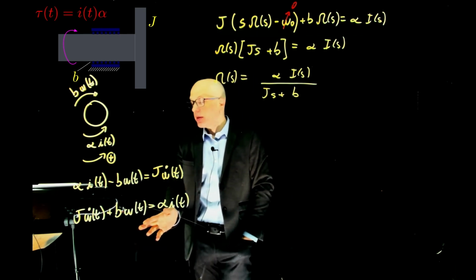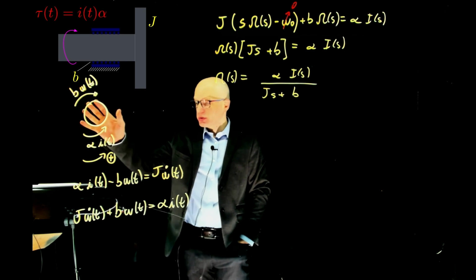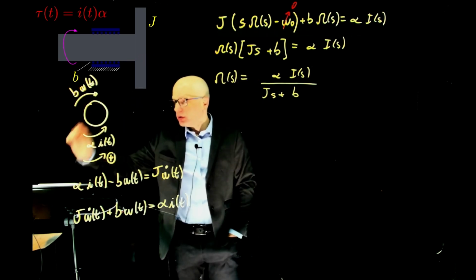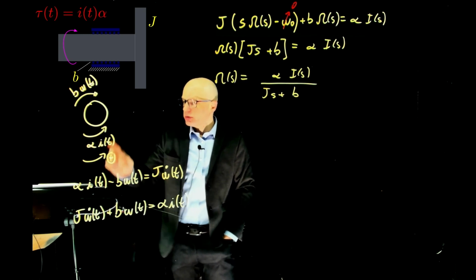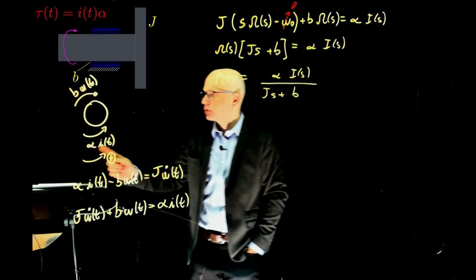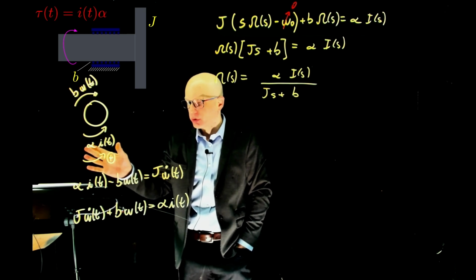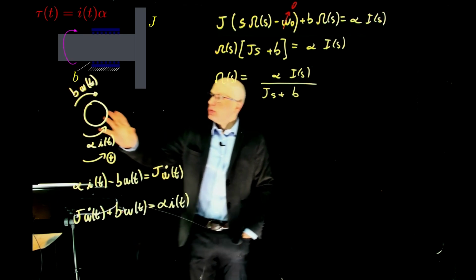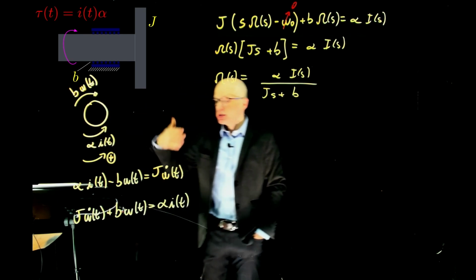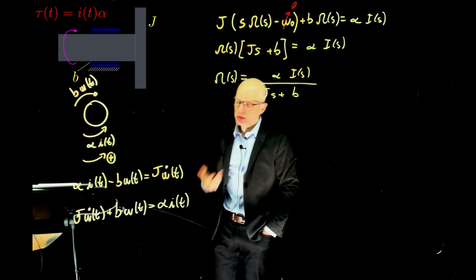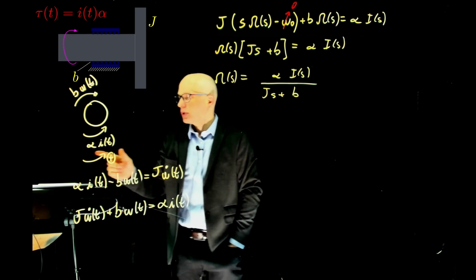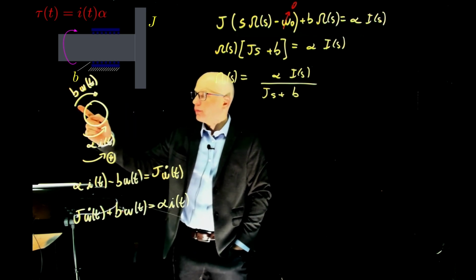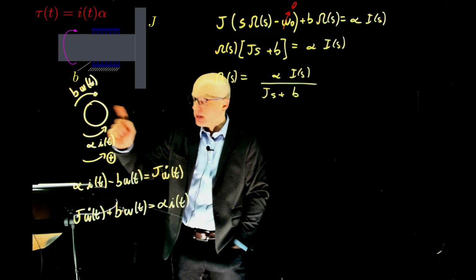All right. Thinking about the system as a rotational system, you're just looking at this shaft from this angle. It's just a circle. The torque is being applied in one direction here. The problem states that the torque is proportional to the current, so this is the input torque driving the load that way. The problem also states that there is friction between the bearings and the shaft. Friction always opposes direction. So if this is applying a torque that way, the system will rotate that way, counterclockwise. Friction needs to apply a torque opposing that, so it's going to go clockwise.